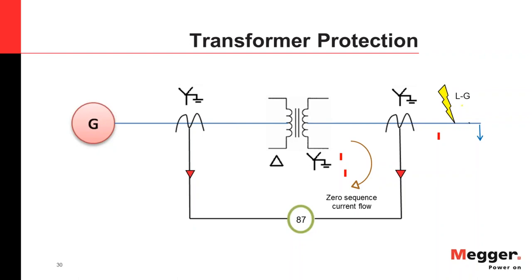I have a question which says, is it customary now to perform only one test for 51P? I have always performed 3 tests by creating a pre-fault balanced system and incrementing one of the 3 phases. Verify 51P for each phase. Best practice. So as I said, it's just an idea of differentiating 51P from 51N.